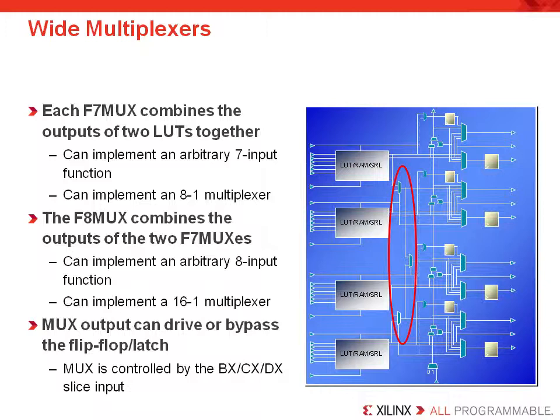What is most important to remember is that each of the dedicated resources has an intended purpose of saving LUTs and improving the speed of your design. Also be aware that if you are going to code for a large multiplexer, you code with a case statement in your HDL. This is required for inference of the dedicated hardware mux.